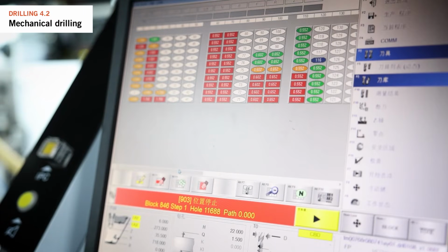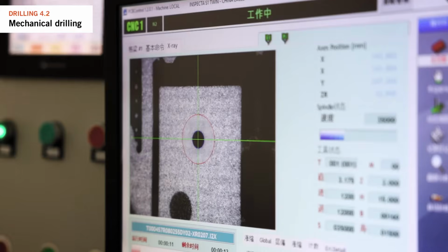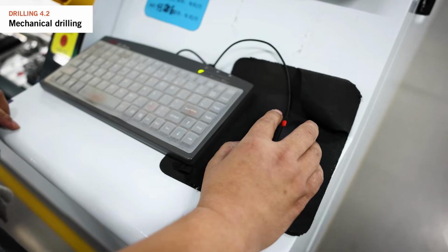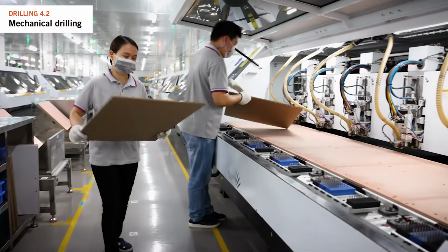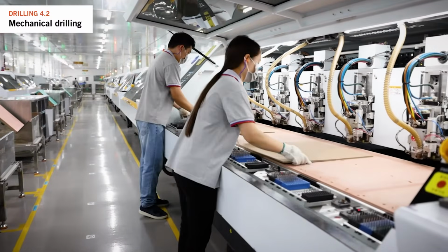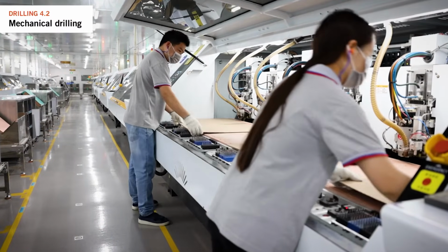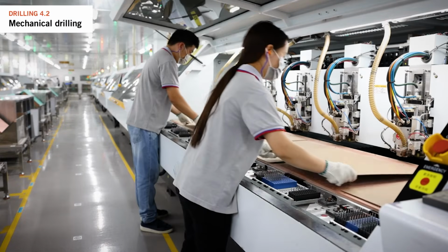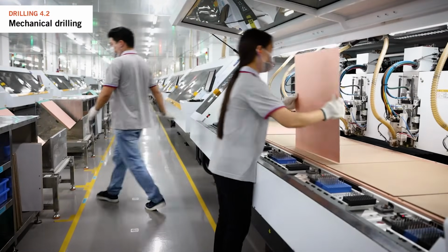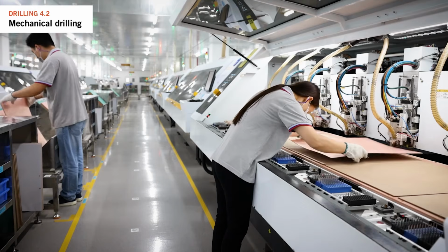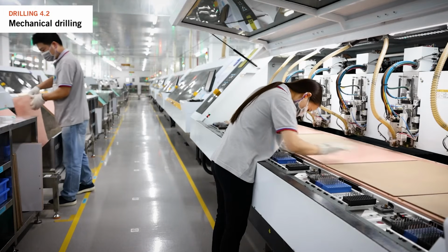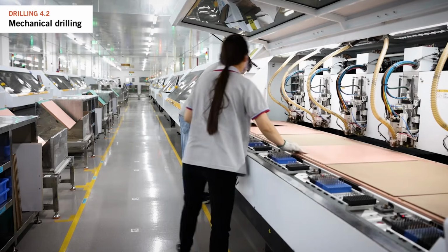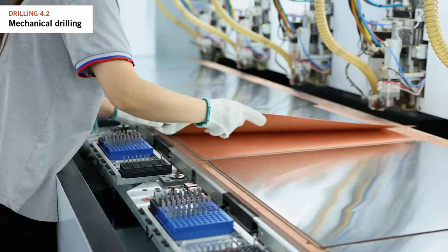First, we determine where to drill, using drill files from the customer data, including positions and drill size details. Before drilling, we place a base plate on the machine bed to prevent drilling into the machine and avoid burrs on the panel sheet's bottom side. On top of the base plate, we stack the panels, aligned using the tooling holes we added in the previous step. Usually 3 panels at a time, but this can vary depending on thickness of the panel and copper thickness.